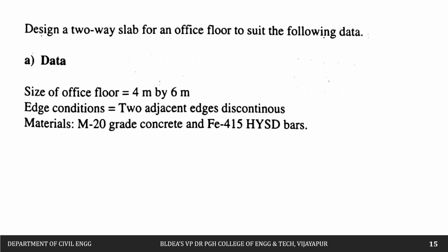Then next, let us try to see another problem. Design a two-way slab for an office floor to suit the following data. The size of the office floor is 4 meters by 6 meters. Edge condition, previously it was simply supported. Here we have two adjacent edges discontinuous.